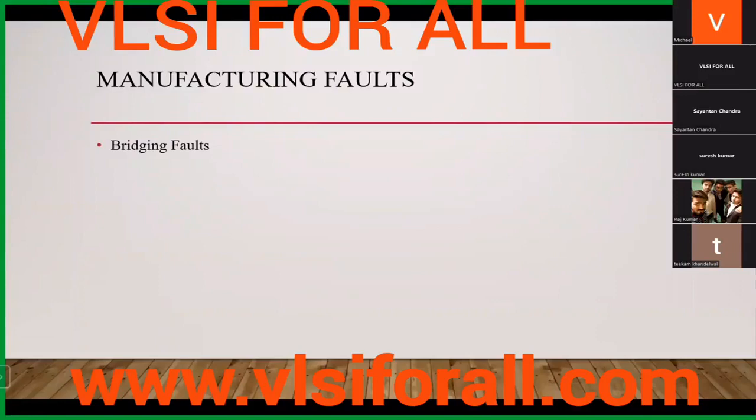As he already answered it, but I'll say that. For example, we have two buffers and the inputs of those buffers are connected. If we want different values on the buffers, we cannot have it because all the inputs are connected to each other. So that is what we call bridging faults. When we move further, we will discuss all these things in detail.